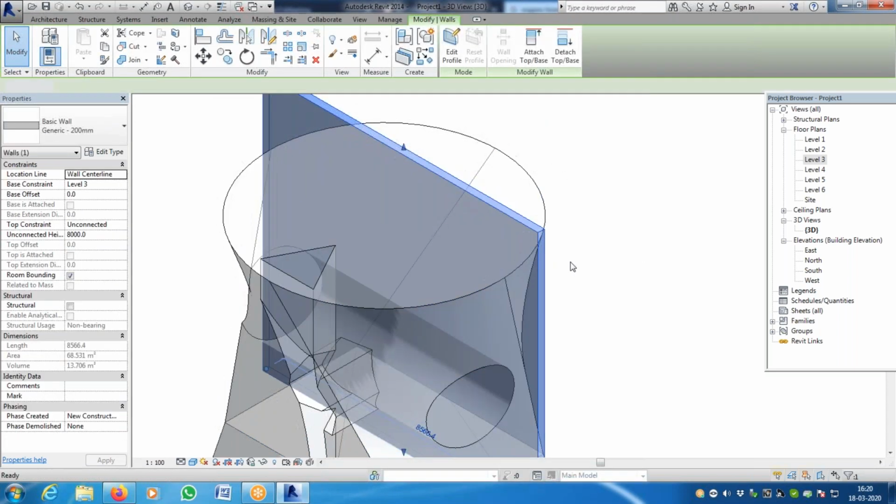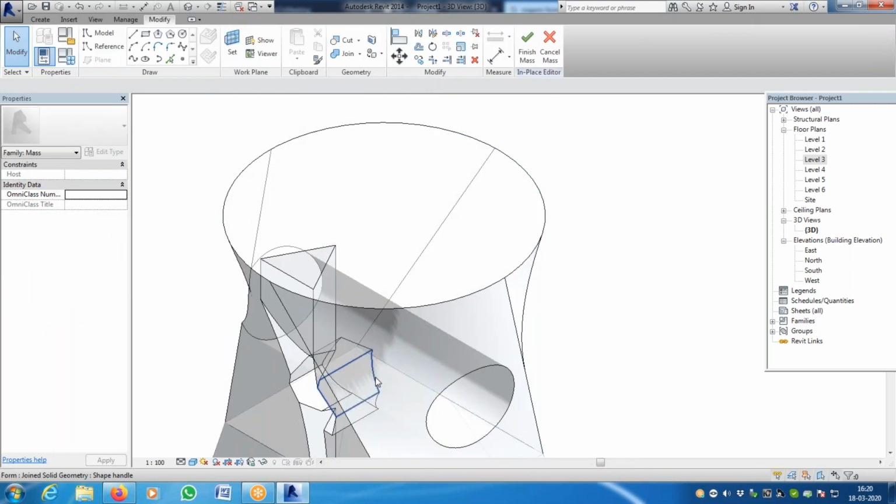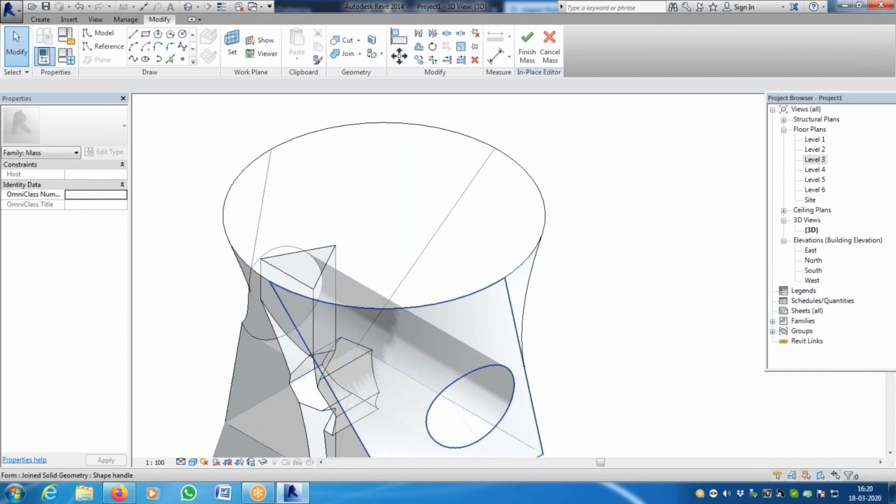Finish. Delete this wall. I think it didn't cut across because I didn't drag that much. Okay, if you want to select something, there's a tool called the Tab key. You can press it multiple times and select what you exactly want. I think I've told you in the last semester. See, I'm using Tab.